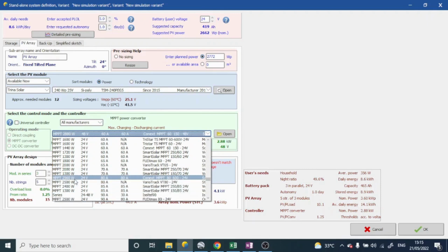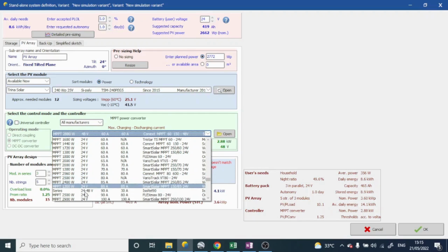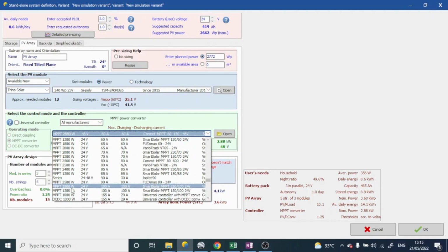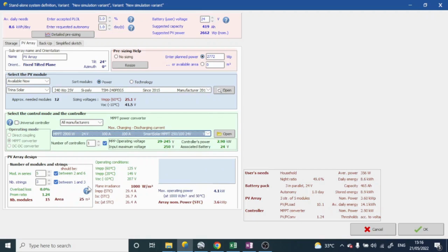So we just select it over here. Let's say this type of controller, if we are selecting, this is a 2560 watt capacity, which is close to our selection. We'll see the other parameters further. If you are getting a higher capacity, like the 2900 watt, which is 24 volt, compatible to our battery bank also, but it is slightly oversized, that is also okay. If it is slightly oversized, it satisfies our demand. From a future point of view also, it is essential to design for a higher capacity of the controller. So we're going to select this controller as per the capacity.